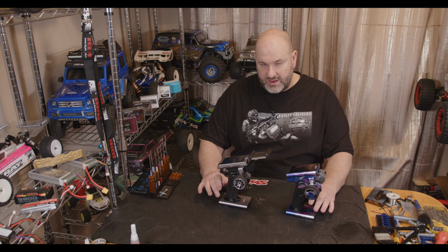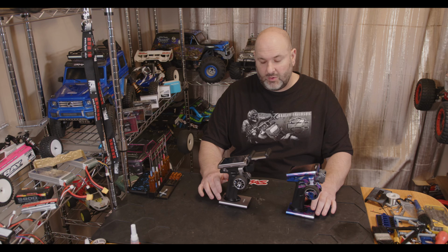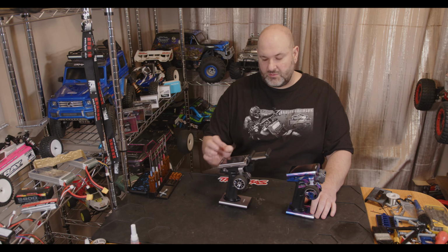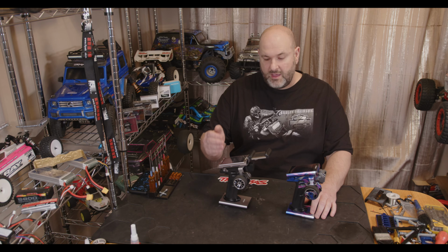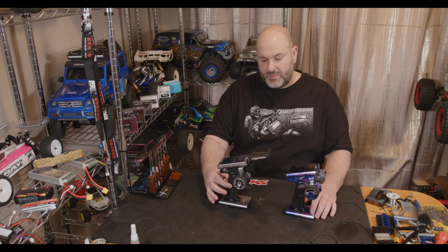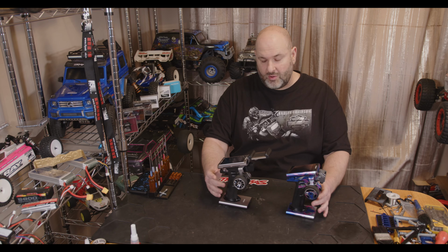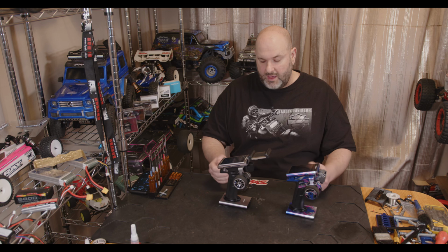If you're running USB 1 or a really low quality cable, you can get a position where your PC physically can't supply enough power to power the power base and the controller, and it'll slowly drain the battery. So if you're playing for hours and hours, you could drain the battery in the handle completely, and then your NB4 or your Pro won't turn on.